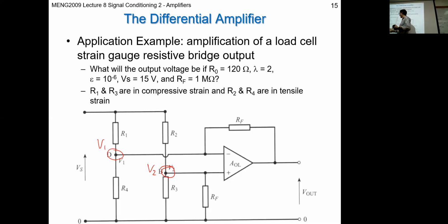Now, R1 and R4 are going to be slightly different because one's increasing in resistance and the other's reducing. But since the strain is very small, you can more or less average it for this purpose to get the input resistance. You could say we can take the resistances without taking that into account. So the effective input resistance is going to be simply half of the base resistance of each of these, so that's going to be R upon 2. That's how we get our input resistance. These are acting in parallel.